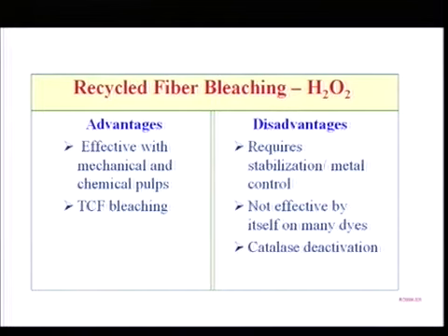What are the disadvantages? It requires metal fixing chemicals, a chelating agent and the soap that goes with it. So, there are a lot of chemicals you need to handle. It is also not effective on many dyes, and if you have catalase, an enzyme, present in your white water, that catalase is going to attack the peroxide, decompose it and take the peroxide away. Then you need to add more and more peroxide, and the process becomes very expensive.